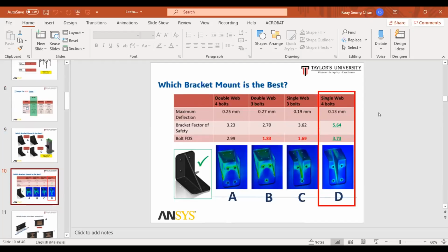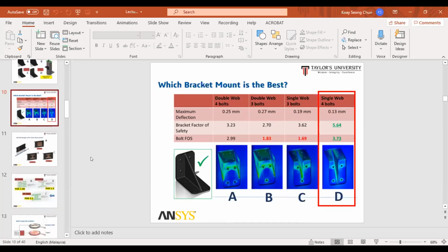Because of how they decide this, they will check the risk, like if this material fails, how serious the accident or the cause will be. For example, the safety factor they need for the lift cable. As I know, they need a safety factor of 40. Yes, because for a lift, if the cable fails, it will cost human life. We will definitely get inside the lift. That's why the cost of failure will be very high, so they set the safety factors very high.